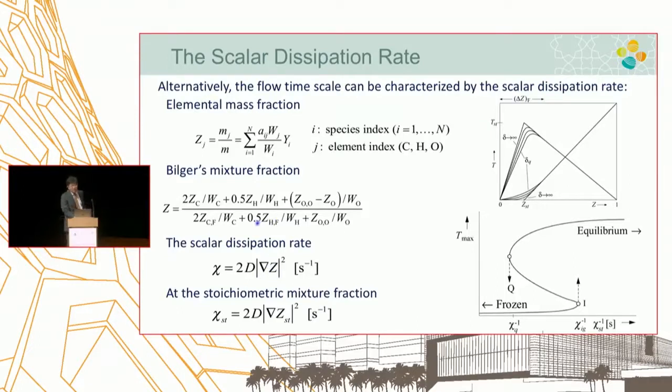Z. The mixture fraction is a conserved scalar, which is one nice property. Without further complication of the derivation, you can think of it as an elemental mass fraction. Throughout the combustion, the fuel disappears and product shows up. But throughout the whole process, the total number of carbon doesn't change, and neither does hydrogen, the H atom. So if you keep track of this elemental mass fraction, it is inert to chemical reaction.